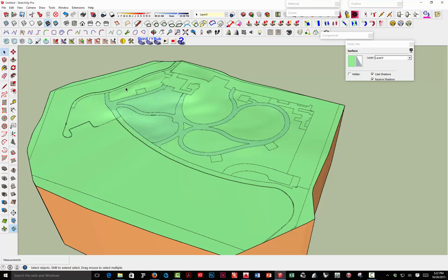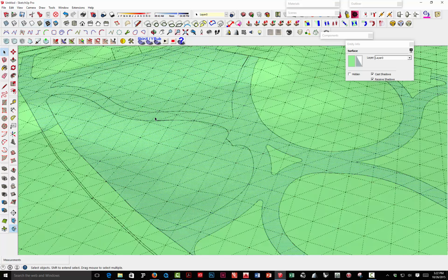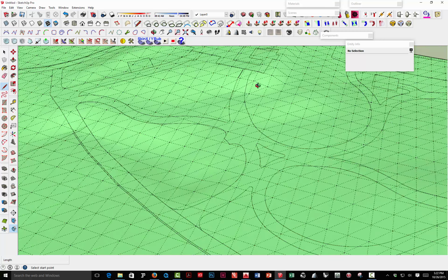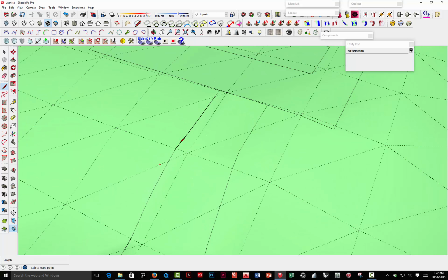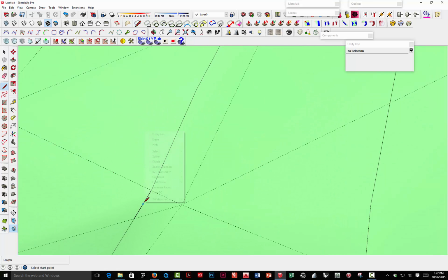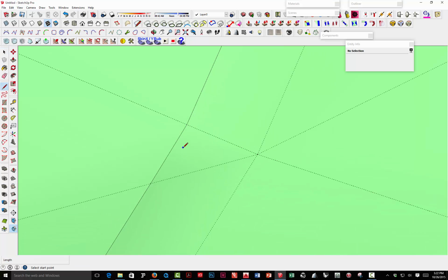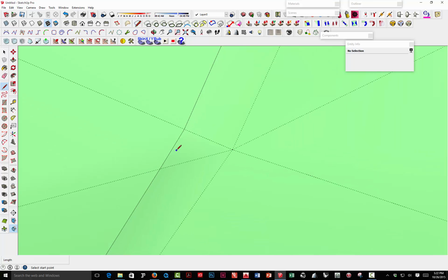And you can see there's a couple here, and I usually turn on the hidden geometry to see that. So when you see a thick line, you know something's going on. Usually I just go in there and delete that, use the line tool, and reconnect those, and as soon as that dark line disappears, you know you've got it. For whatever reason, the plugin just doesn't quite get that. I can see there's a little teeny line segment right there that it doesn't really like. Since I know this is a planar surface, there's no need to have three pieces of line in there.